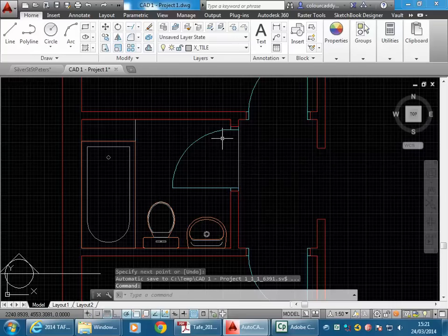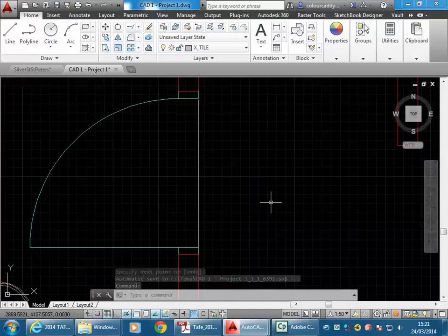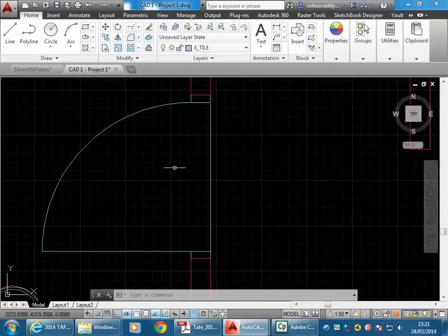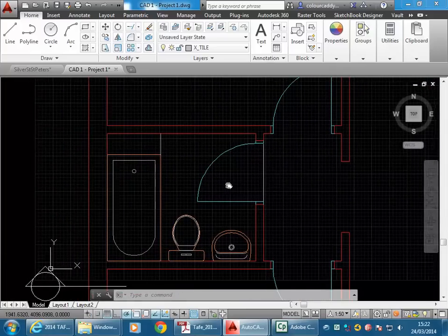Now they can actually go the nicest way if you're doing a really high-end job and you want to make it have just the nicest finishes you can. Then the best way is to have the tiles finished under the door edge, so you don't see the tile edge sticking out under the doors, which is a nice way of finishing it off. But this is okay as well. You'll see the tiles, but it's still waterproof, which is the main thing. That's fine for a project like this to do it that way.